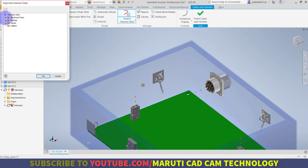So now let me review all this information. As you can see, in total there are 4 parts: E1, L1, L2, P4. Here, one splice is there that we have created in Autodesk Inventor, and these are the wires. Within these wires, you can see the type of the wire and the reference designator is also mentioned, from which designator you have to start and from which designator you have to end. And simply click on OK.